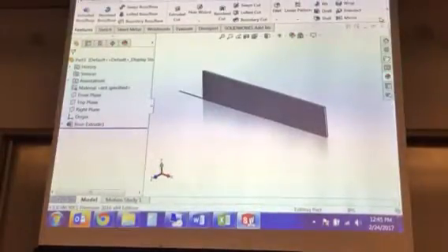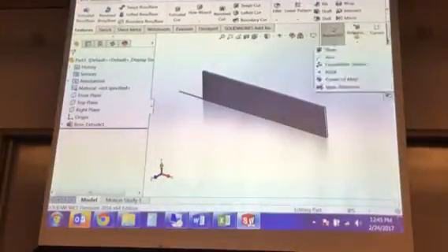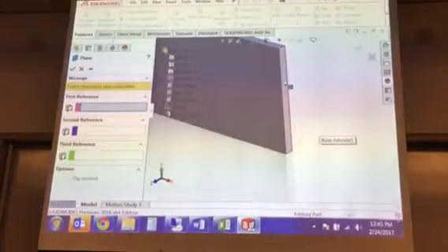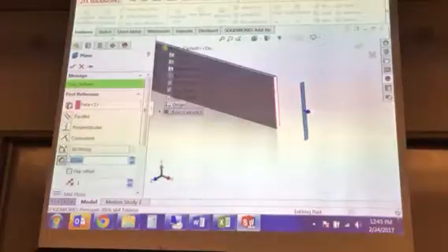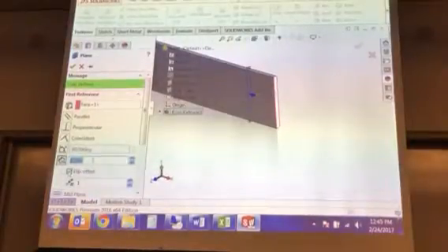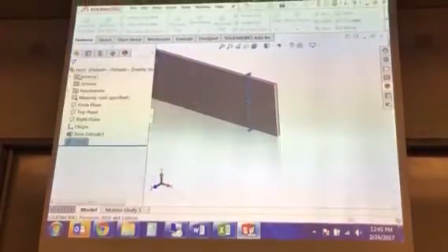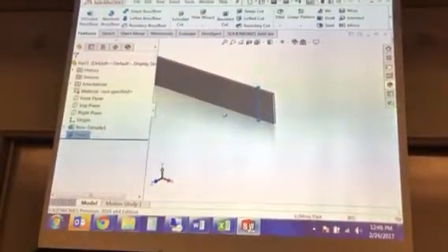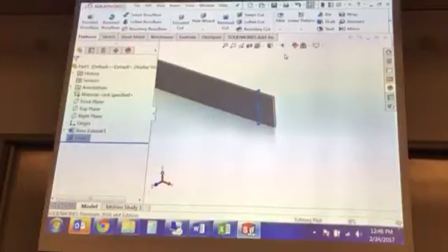So you guys know that you have the option to create additional reference geometry, and I can just offset that plane 6 inches, and it's already in there for me. Okay, so now I can draw my spline out from the side on that plane.